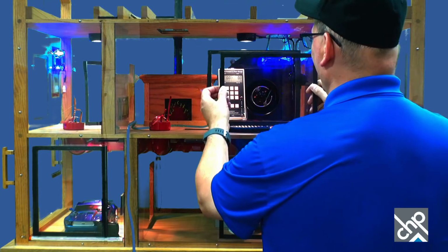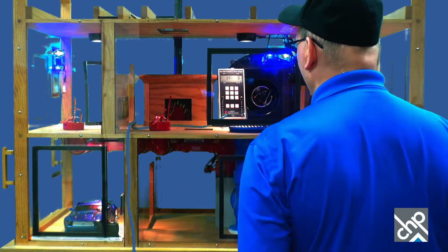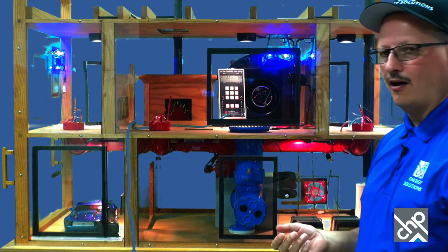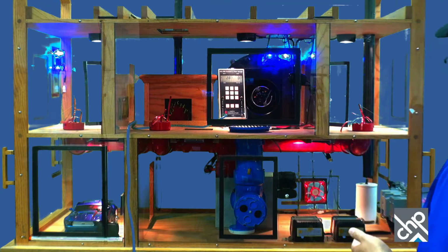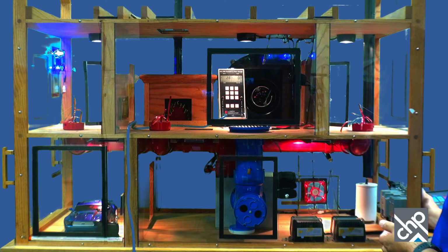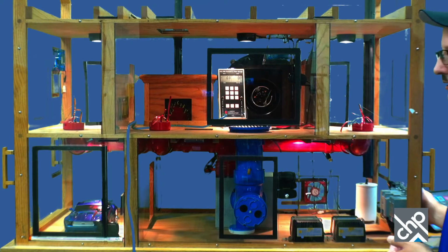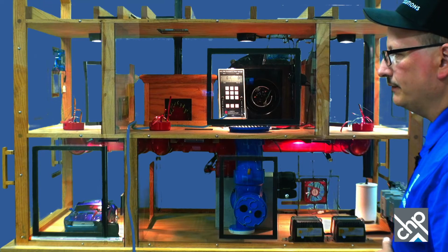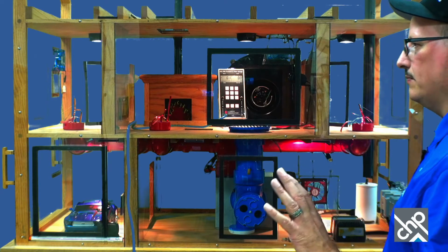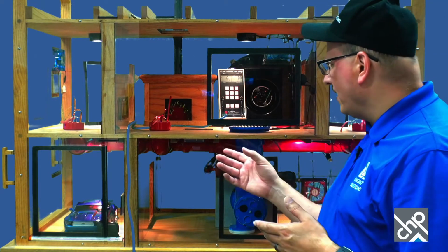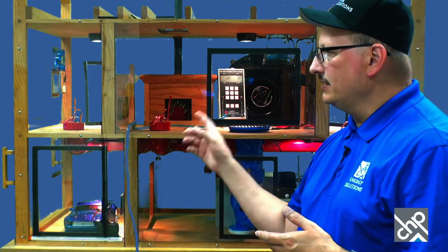So I'm going to put this back on, and as you see now, as soon as I put that back on, the pressure went more negative. So I'm going to turn off all the exhaust fans. Then I'm going to turn them back on individually. Now when you're measuring, I've got the manometer in here. I didn't really mention that. It's measuring pressure between the house and the outdoors. So that's the pressure that you're seeing.